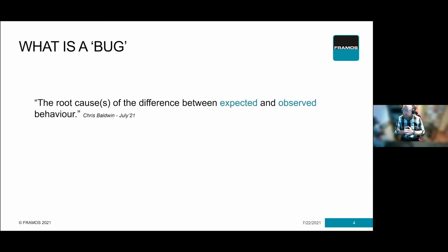So, for example, if you're complaining about resolution not being very good, but you're looking at a compressed image over a JPEG stream, definitely look at the compression to see if that is actually causing the loss of fidelity to your raw image, rather than tweaking the sensor continuously. Because if you're compressing something heavily, there's no way you're going to be able to recover the image quality through changing the settings on the sensor.